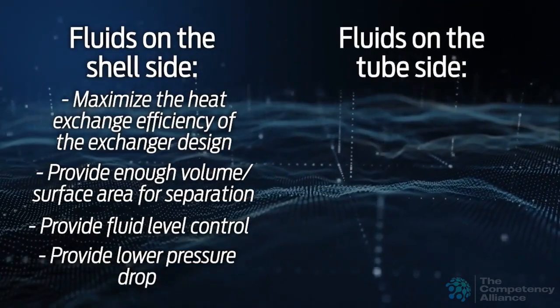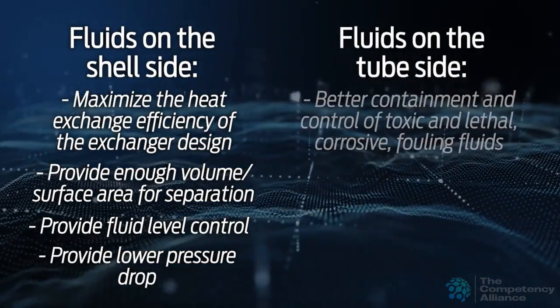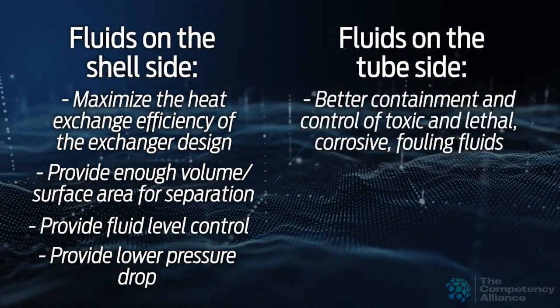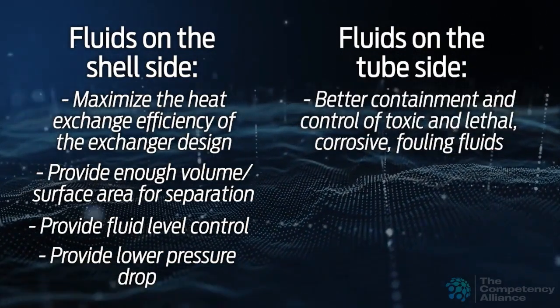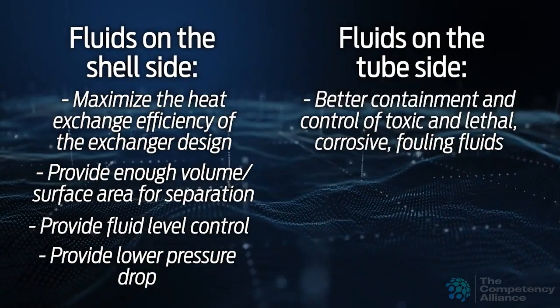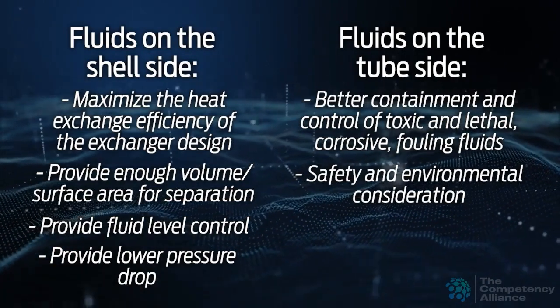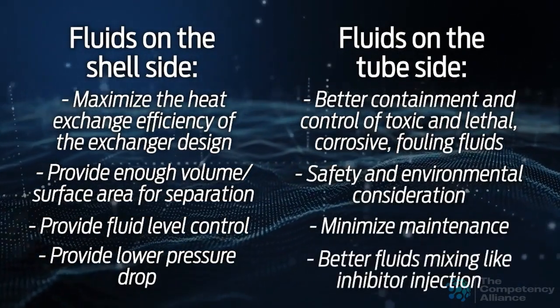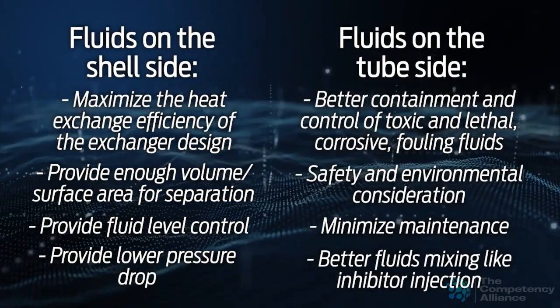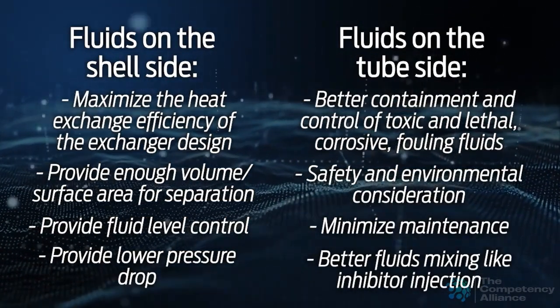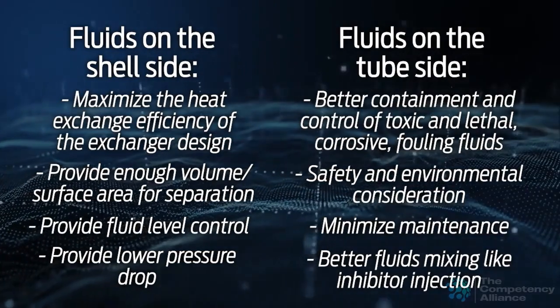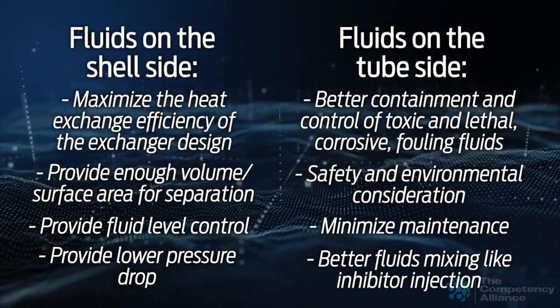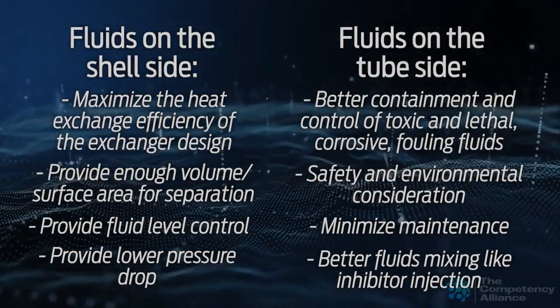Fluids are often placed on the tube side for better containment and control of toxic and lethal, corrosive, fouling fluids, for safety and environmental consideration, to minimize maintenance, and for better fluids mixing like inhibitor injection. These are not mutually exclusive. Some priorities must be established, and some compromises may be necessary.